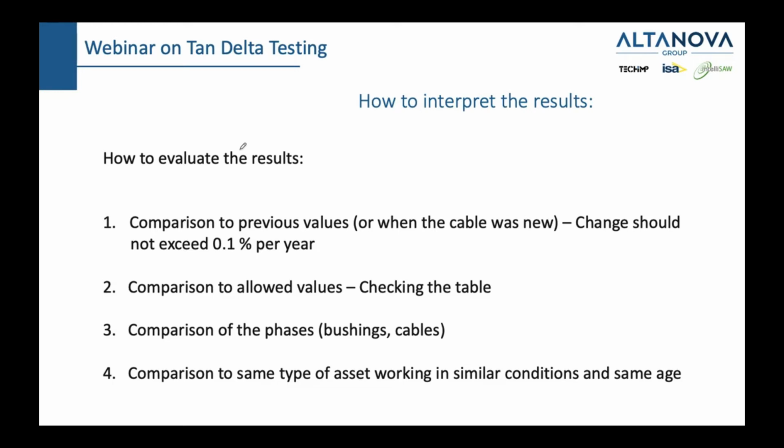Grounding is essential because we measure also the current going through the ground. And one thing which Mr. Simone Meneghin mentioned, because we did have that same question in the morning session, is you need to understand what is the value of this negative tan delta. Are we talking about minus 7% or minus 0.01%?